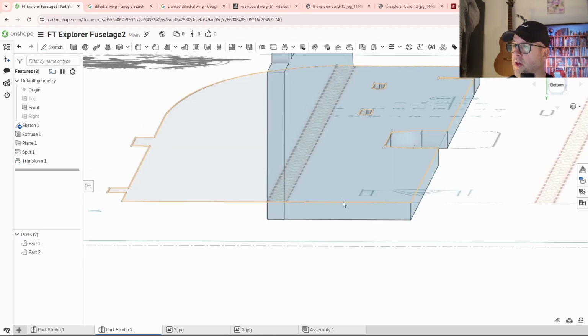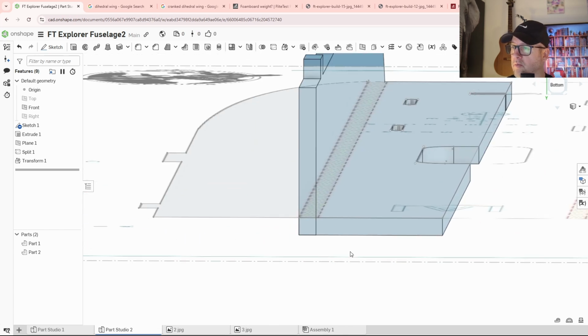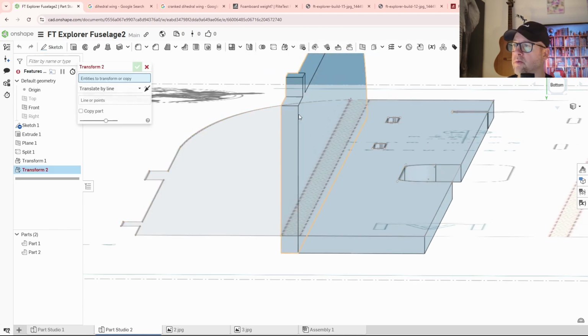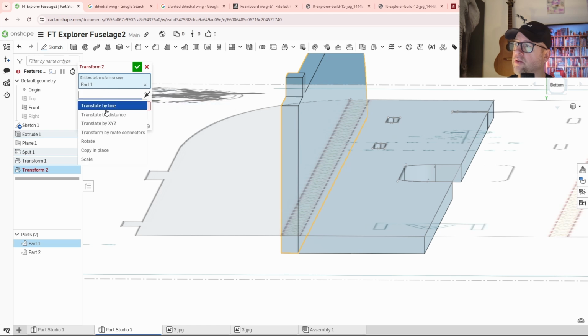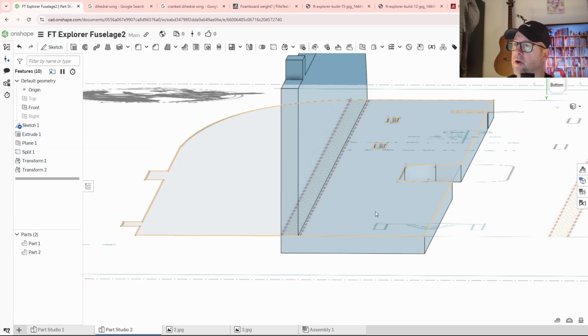There we go. May want to raise it up 4 millimeters because they say this is a hatch area. Yeah, so I want to raise this 4 millimeters. So I want to transform XYZ, and we're going to -y, -4. Enter. There we go. Perfect.